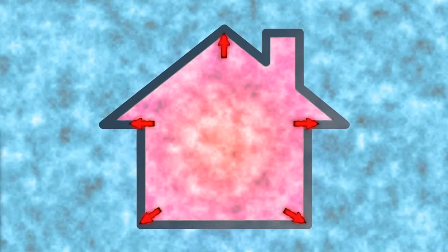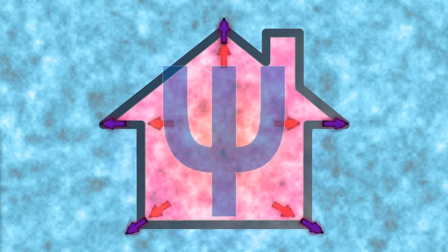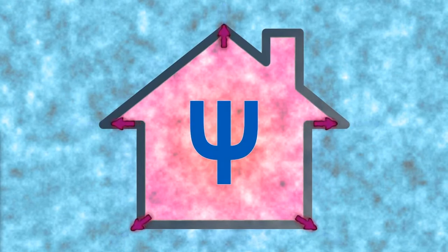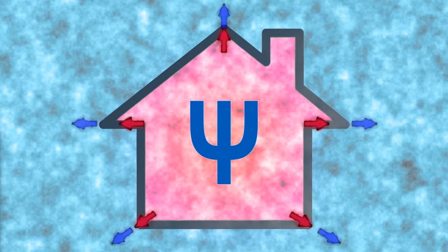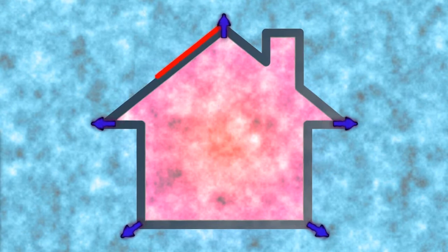Thermal bridging at corners and junctions is accounted for using an additional value for linear thermal bridging, known as a psi value, but in most cases these are addressed using standardised pre-assessed details to limit heat loss. The easiest way to visualise the way thermal bridge-free design works in practice is to simply imagine drawing a pencil line around a cross-section of the entire heated envelope of the building.